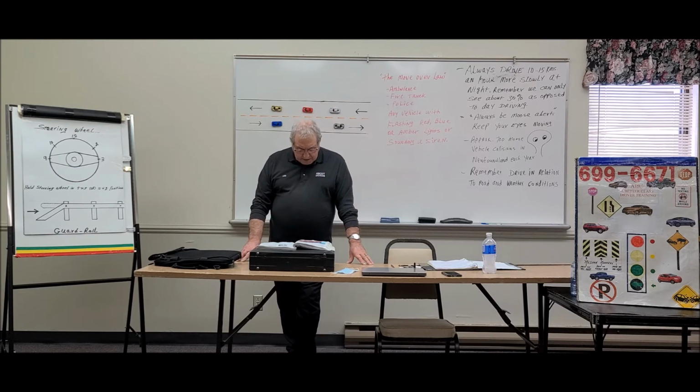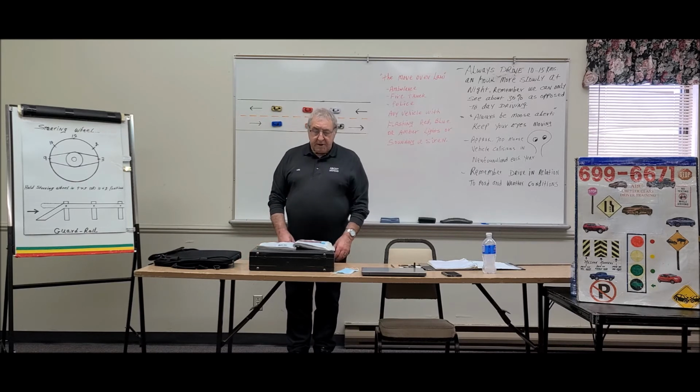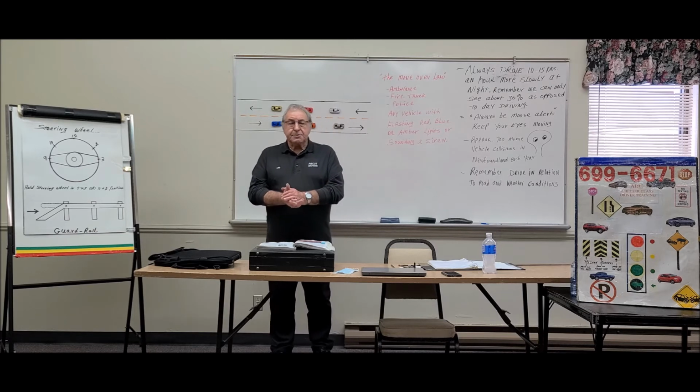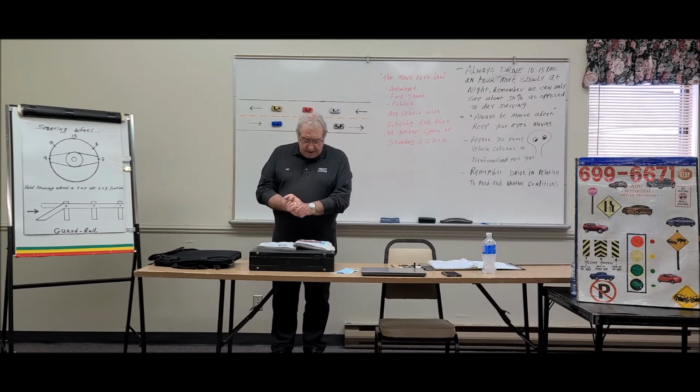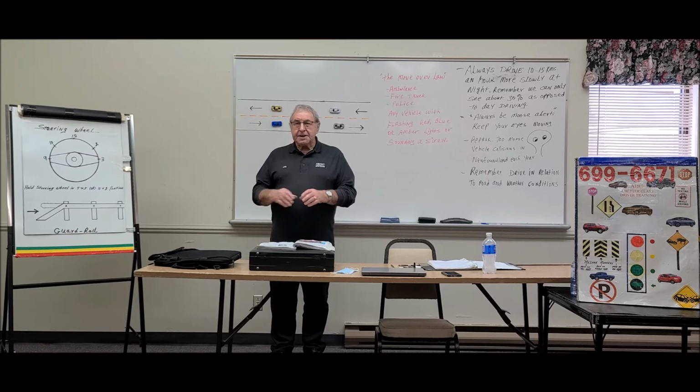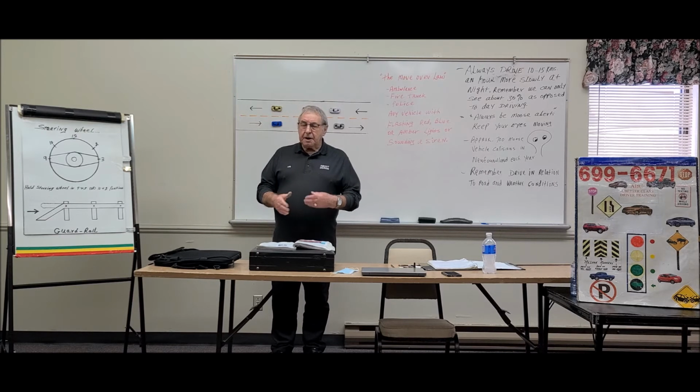The next component there is a clutch. That will be typical of a standard vehicle or a manual transmission, whereby you're pushing the clutch to disengage the engine from the transmission. That's what the clutch does, so that you can shift gears. Of course, once you shift into the appropriate gear, for example, when you're starting off you would need first gear because that's where you need most power, and you would let the clutch out slowly once you've got it in gear and accelerate a little bit at the same time, and then you would find your car wanting to move away, move along.